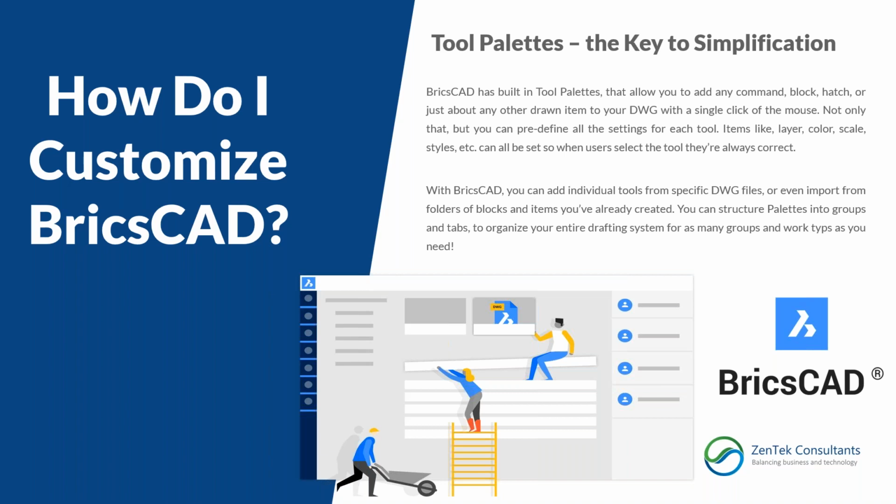Now, the other thing that's really nice about that, because there are other CAD systems that have tool palettes, is that not only do we have the ability to build and customize drawn items, we can actually build and customize tools, commands, and macros right on our tool palettes. In other words, we can take effectively any command or any tool that we have inside of BricsCAD, add it to the tool palette and tweak and customize it, even to the point of doing macros where we could put in 3 or 4 steps, like open the drawing, zoom extents, hit the plot command, change to this particular page setup, etc. We can actually build and code that into a very simple tool palette system.